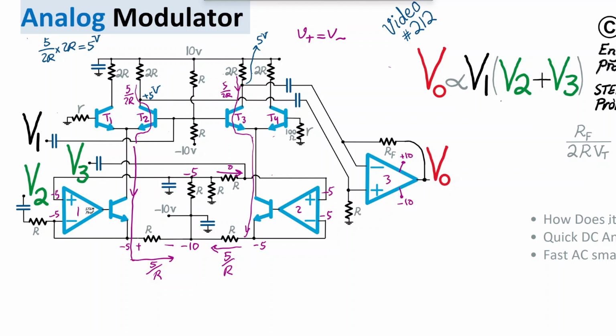And look at the decoupling caps we have. So those decoupling caps would separate and decouple DC from the rest of the circuit. For DC analysis, there is no current that passes through R here, because as I said, decoupling caps are preventing DC from being transferred. So there is zero DC current, and therefore there is zero DC voltage here. As a result, effectively this becomes like a buffer and zero DC voltage here, and therefore V out is zero DC. So no DC voltage shows up at the output.